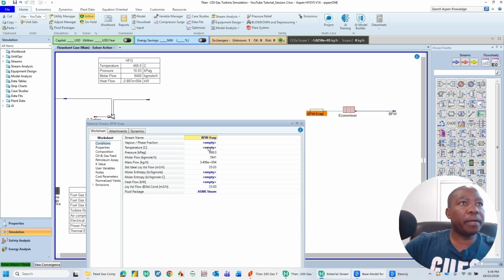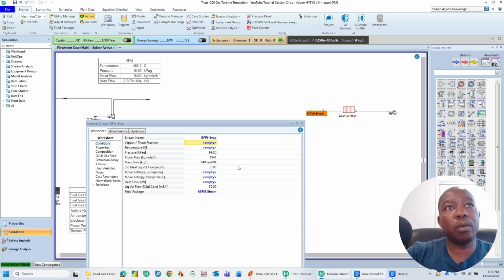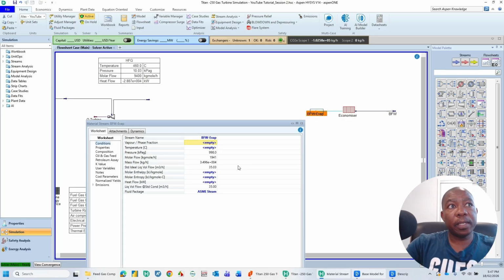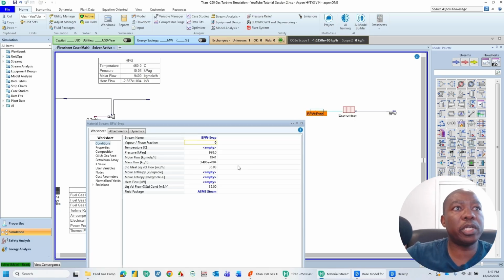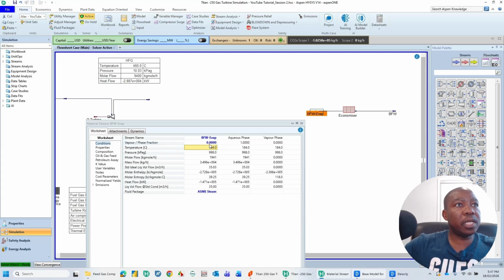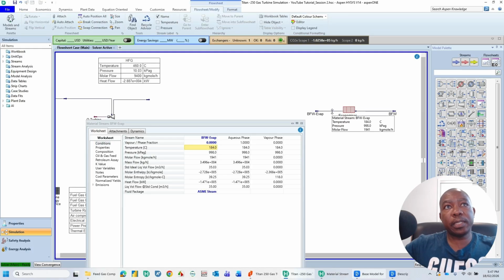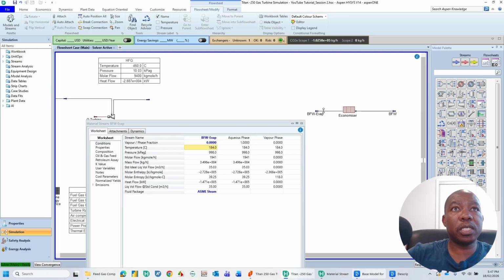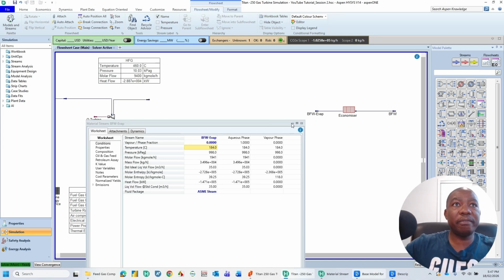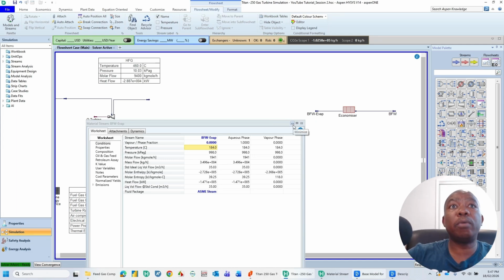And then the temperature, we don't know the temperature, but we know that this stream is still liquid phase. We're going to force it to be liquid, right? And then HYSYS will calculate the saturation temperature. So I've got a vapor phase of 0, and then the saturation temperature is 184. So see, now it's dark blue. Now I know this is fully specified. Then I can continue to the next unit operation. This is how I find the process to be relatively simple, and it's not that confusing.